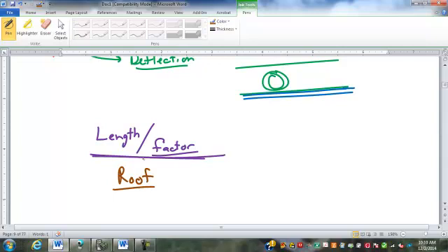Typically, I always tell people, if you put tile on concrete or tile on a wood frame floor, it must be specifically engineered for it. I've seen it actually crack a 12-inch tile down the middle because the floor flexed enough to cause that kind of stress on the tile. So your roof, like I said, gets a little bit more allowable flexure.